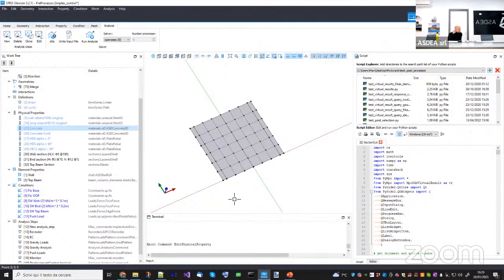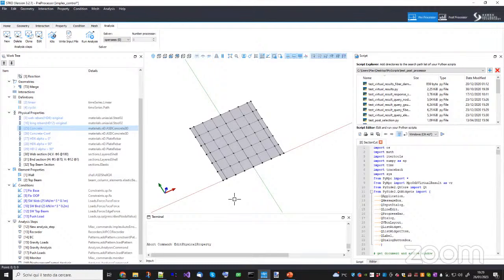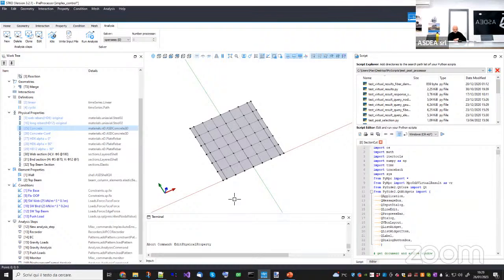No, I mean, it can be due to many things. What kind of constraint handler were you using? Because we found that when you have multi-point constraints and you use the transformation method, we found some issues when you have many partitions. We still have to understand why. It is something inside the transformation method in OpenSees that sometimes can give problems. So when we see problems like that, we switch to the penalty constraint handler.